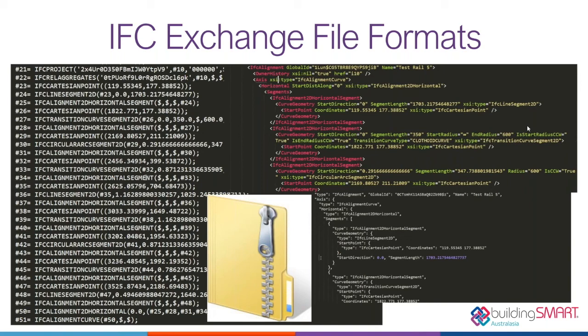Again, I think validating this is an important part of getting this right. And I think the other thing that can be frustrating when using IFC is if you don't get many warning messages about when things aren't recognized or aren't used, even when they are in the IFC. The topology is not consistent. I have to research that. I'm assuming that one's Revit. Again, maybe we'll chase up on this.